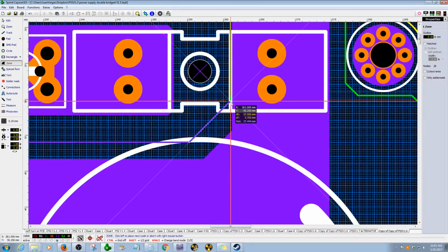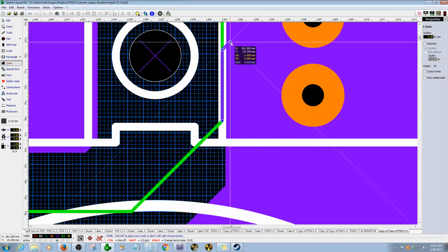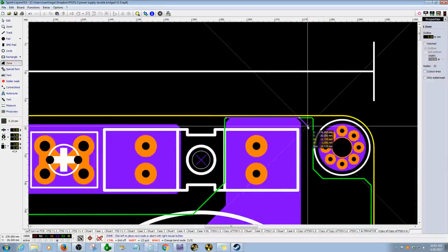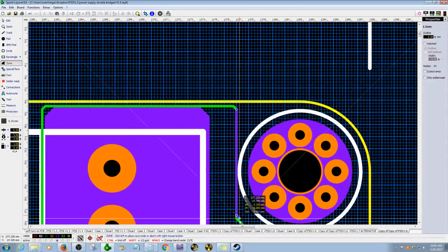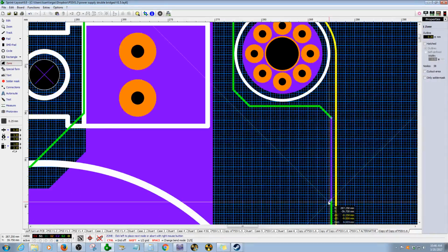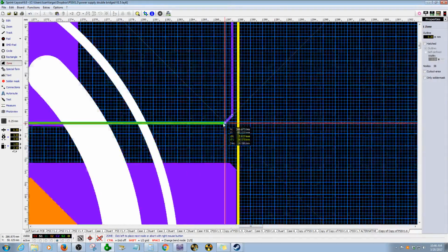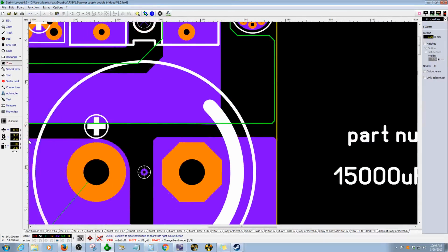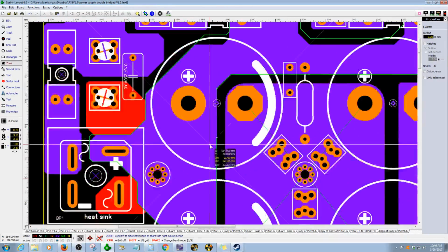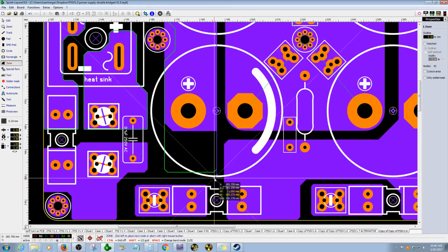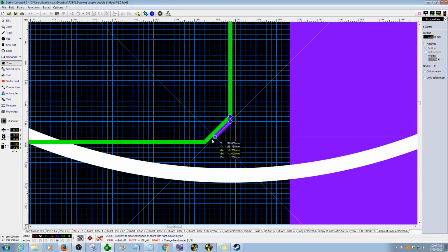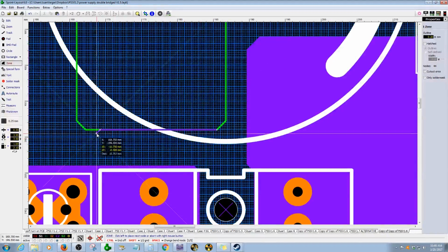The copper area, we can use 1 ounce, and we can use solderable areas to reinforce the current that is going to travel throughout the copper area. So also making everything thicker, wider, will help lower the resistance on the circuit. We gotta keep the resistance as low as possible.